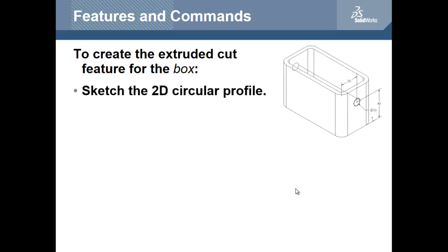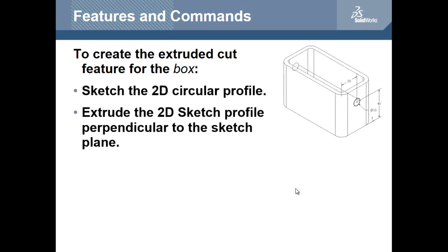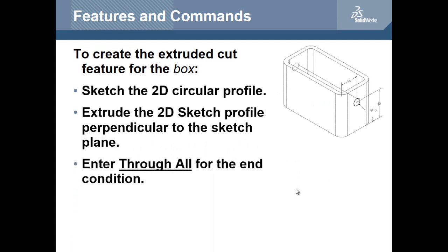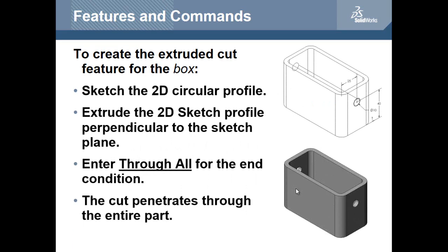To create the extruded cut feature for the box, sketch a two-dimensional circle profile. Extrude the two-dimensional circle profile perpendicular to the sketch plane. Enter through all for the end condition. The cut penetrates through the entire part.